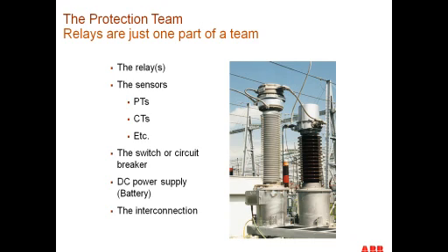The relay can't detect a 2,000 amp current by itself because it would have to be so massive. So we have current transformers that take that 2,000 amp current to a 5 amp or a 1 amp level, so it can be safely applied to the relay. And we take that voltage that could be anywhere between 1 kV and 765 kV, and lower it down to a 120 volt level, again to apply to the relay, so the relay can be operated at a safe level.